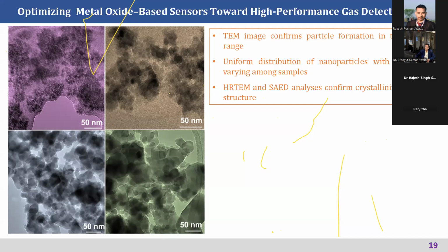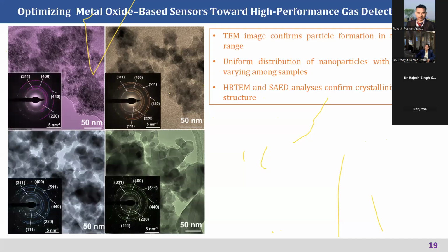The electron will interact with these features and give secondary electrons or backscattered electrons. Those secondary electrons will be analyzed using detectors. That is how the electron microscope works. It works in two modes: the scanning electron microscope and the transmission electron microscope, which is one of the sophisticated instruments where a thin layer of your sample is kept in the electron beam. Whatever electron beam is incident on the sample and gets transmitted, these transmitted electrons are analyzed with a suitable detector.